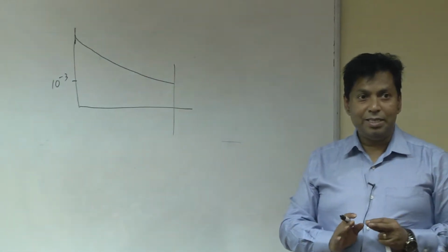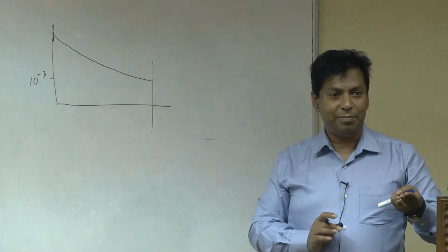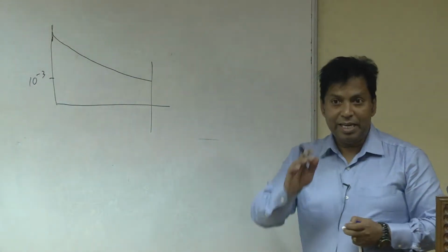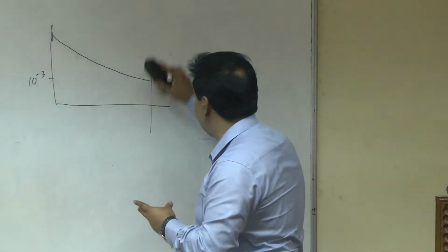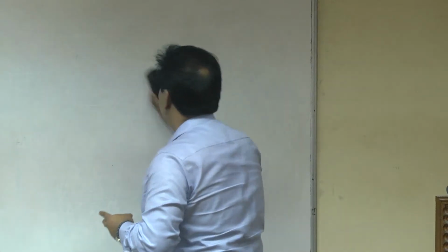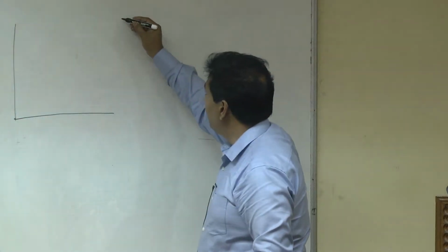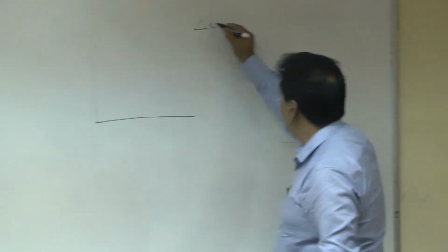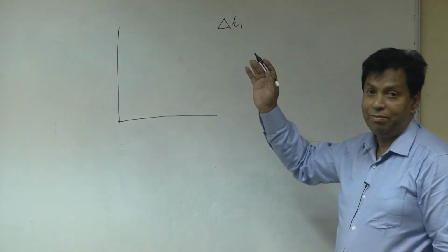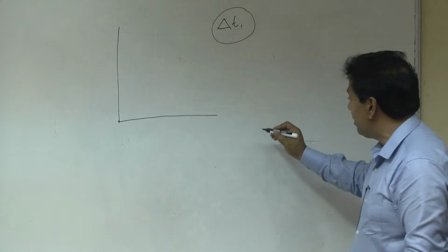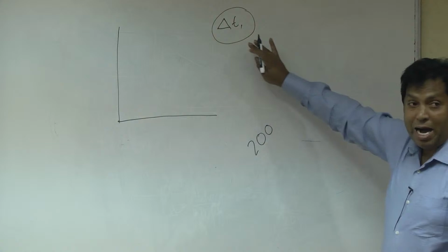And for the unsteady case, we actually have two types of iteration. One is called inner iteration and the other outer iteration. Okay? So it is different. That's why you see it's like a pulsatile. Okay? You see it in there. So this is steady state, and for the transient case, you saw that you have two things: delta t, the time step, and the iterations, how many iterations per time step. Per time step, the maximum number of iterations, you already have chosen 200, right?